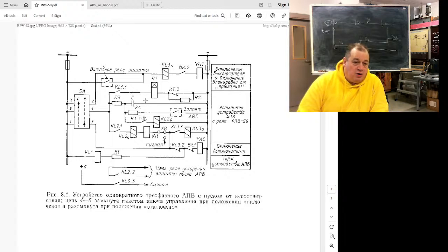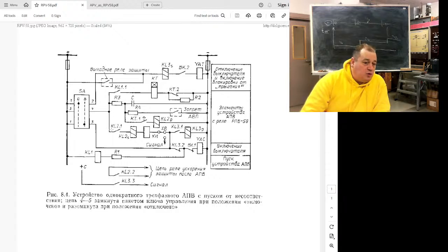Remember I showed with a finger, oil, paper or capacitor. This capacitor is charged through this resistor to the operation voltage. At the moment these time delay contacts close, the capacitor is discharged to interim relay number 2. Interim number 2 closes, and first what it connects, it has two coils, one voltage, one current. The capacitor discharges through the voltage channel. This contact closes and connects the current coil to this voltage source.